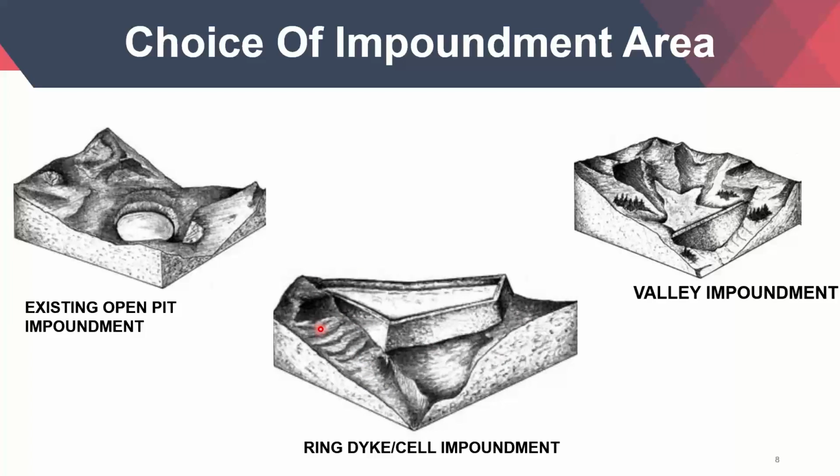dams to fail, because the more filling of materials on an even terrain, the more chances are that the dam might fail. So these corners, they are the most dangerous spaces for the dams to fail, because of accumulation of tensile stresses or low effective stresses.